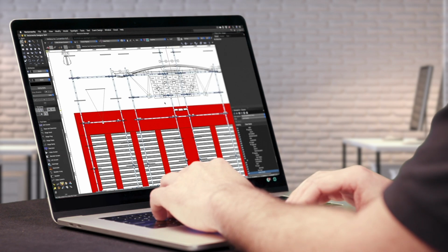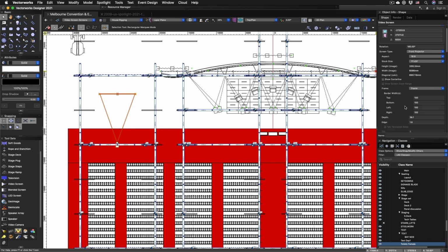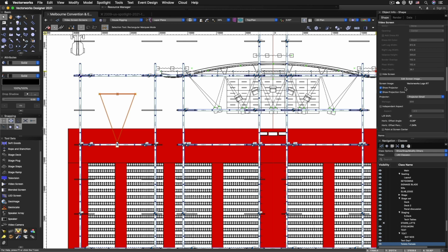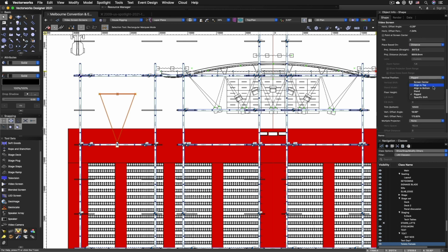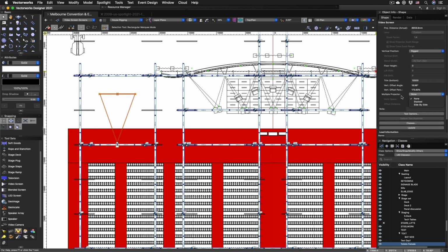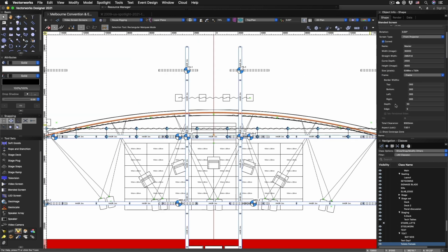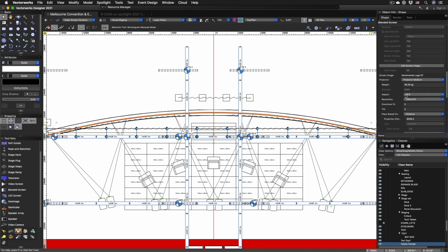Now let's take a look at a regular video screen and projector. Here we can see all of our frame information, show the coverage zone, what kind of screen support, edit the screen image, choose what kind of projector we want to show in the document, and choose whether that projector is placed by the lens type or by the distance. We can also set up our projector to be rigged, on a stand, aligned to a specific part of the screen. We can even show multiple projectors. Upstage, we have a blended screen. This one here is set up to be front projected. We can see the different width values for them. We can even show the coverage zones just like all the other tools.